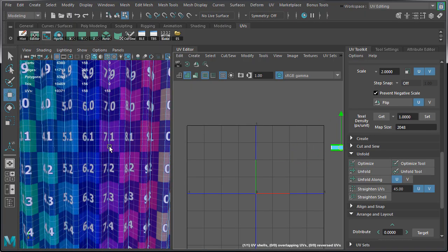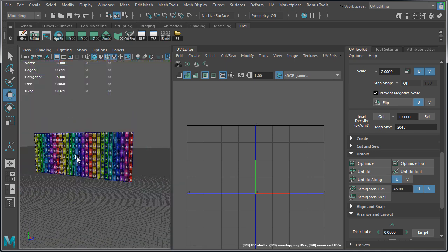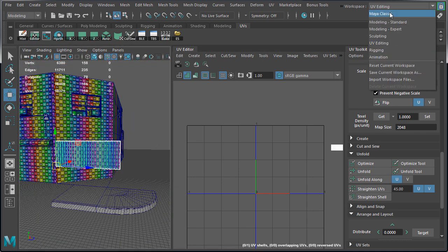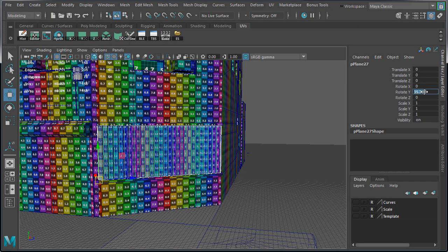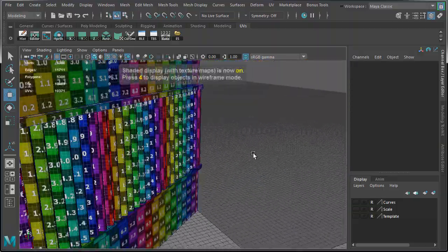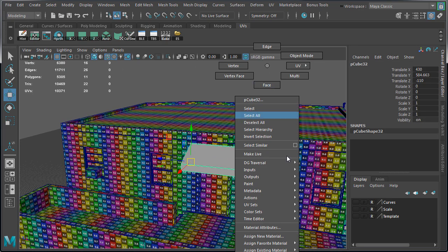We're going to move the UVs out of the way, outside 0 to 1 space, delete history, and put the rotation on Y back to 35.707, placing the window shutter back into position. We're now done UVing the window shutter. Now let's move on and complete the awning.